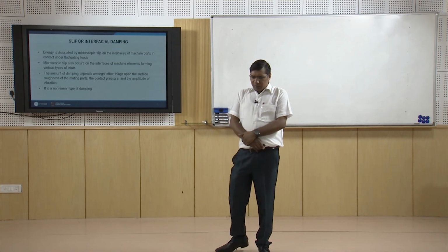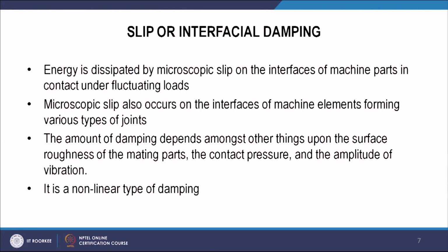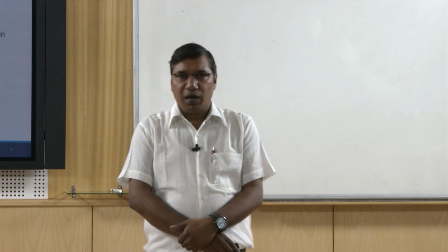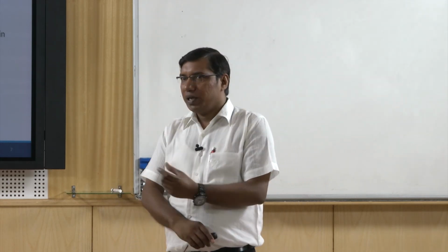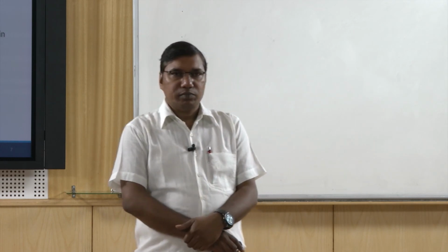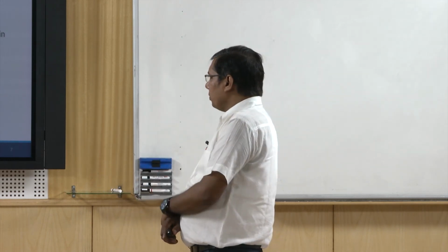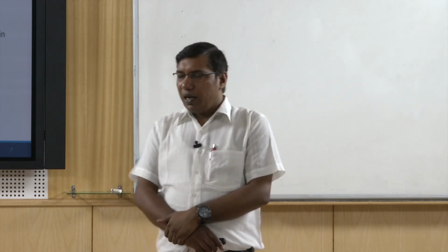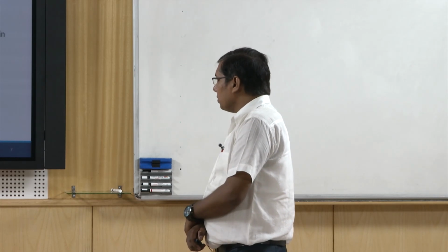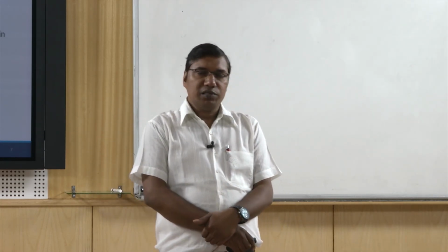There is one more type of damping, that is interfacial damping or slip damping. We have several mechanical parts, and there is roughness between these parts, and when they come into contact there is some micro level of interfaces and rubbing, and that makes the energy loss, energy dissipation.